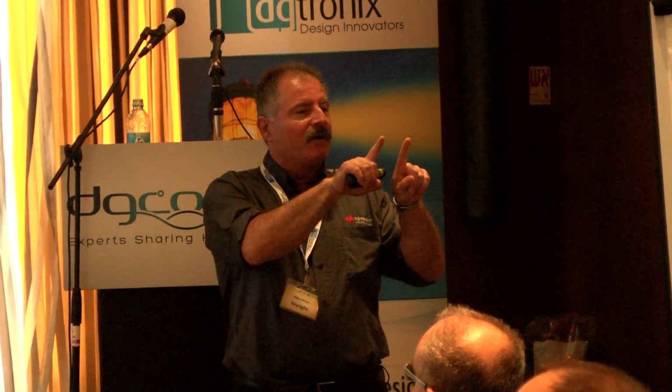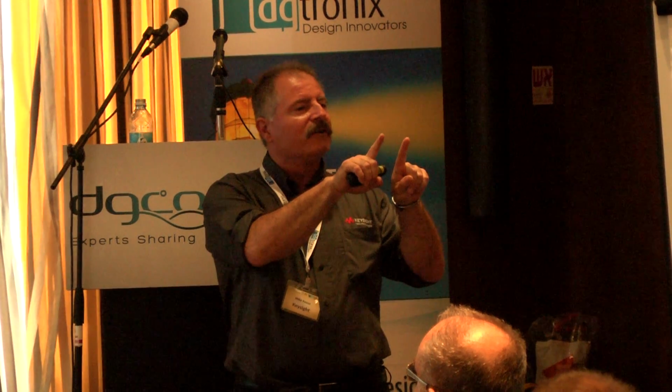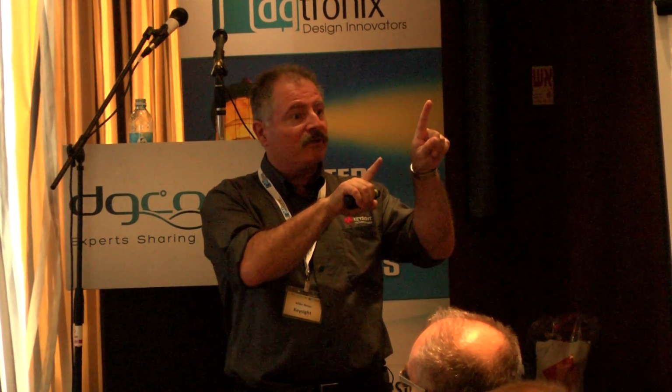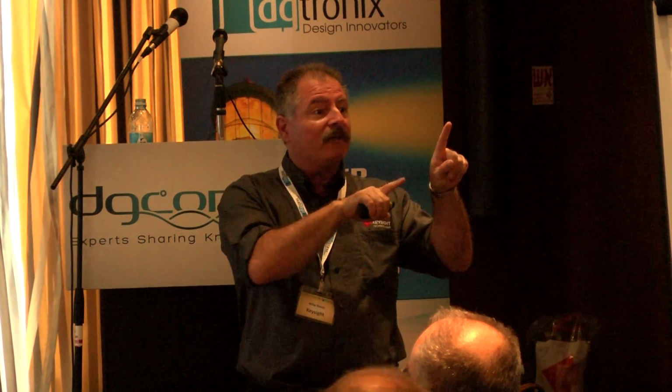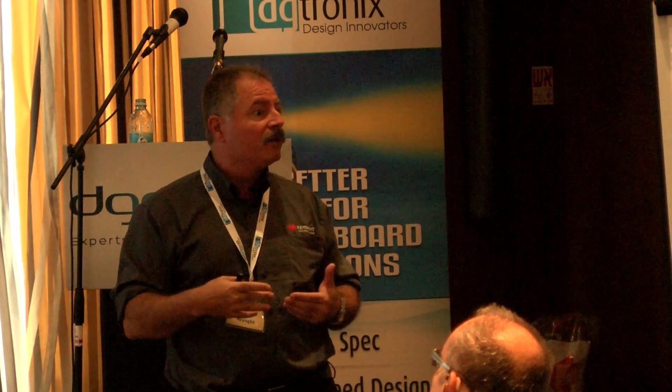Well, there's a weave in the FR4 fiberglass, and if you have one side of the differential pair over epoxy and one side over a weave, you're going to get two different relative dielectric constants and different propagation velocities, which would create skew and potential mode conversion and crosstalk. So that's not a good thing. This is something that many people do with high-speed channels on FR4.